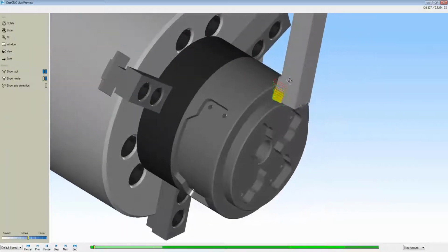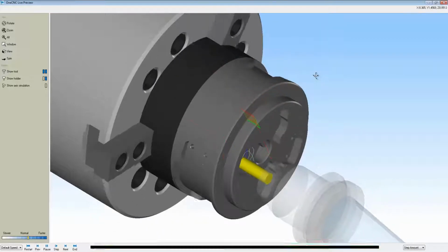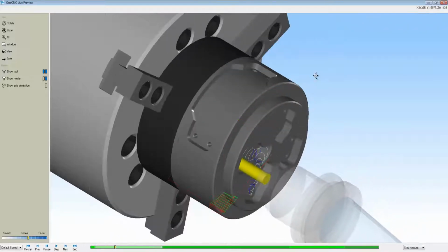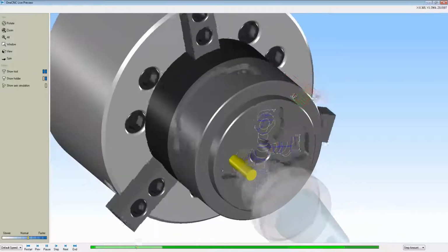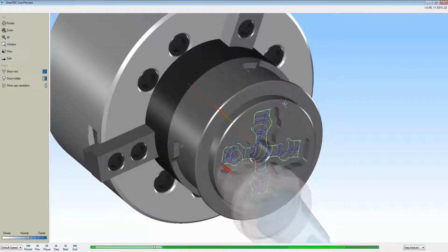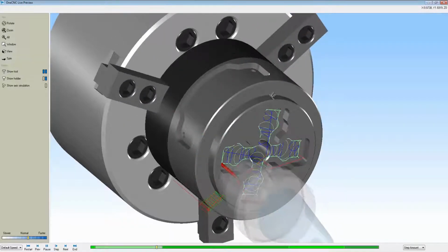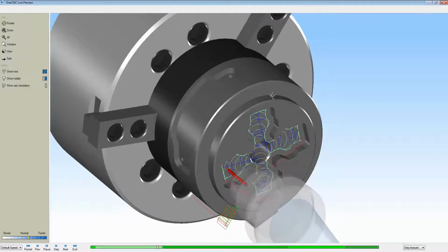Now here's our standard 2-axis roughing, facing, and a finish operation. Now we switch tools to an axial end mill, and we're performing axial high-speed pocket machining. Very, very nice. Now of course this can be rotated. You can speed this up or slow it down if you want. We're performing a peck drill operation on those 8 holes.